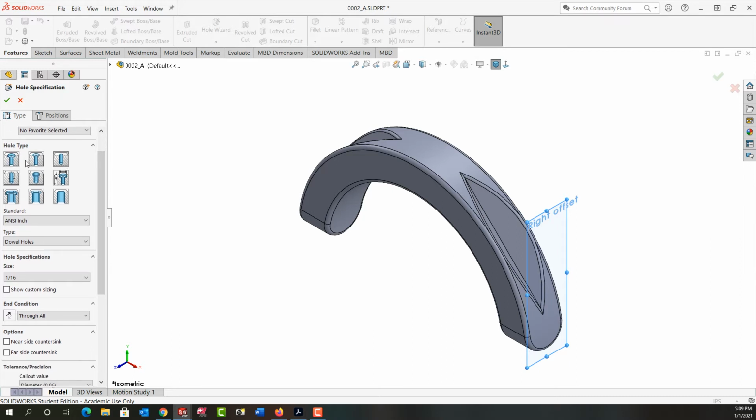Here we have 9 different hole types: counterbored, countersunk, just plain old drilled or reamed holes, tapped holes, NPT tapped holes, or when none of those will work, a legacy hole, design your own. We also have slots, counterbored slots, countersunk slots, and just straight slots. For this particular hole, I want just a drilled hole.